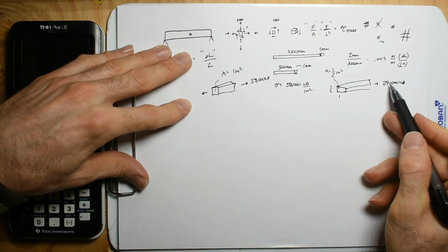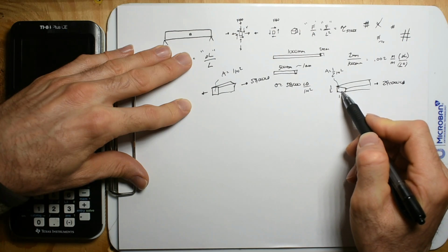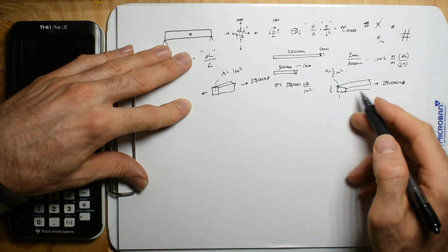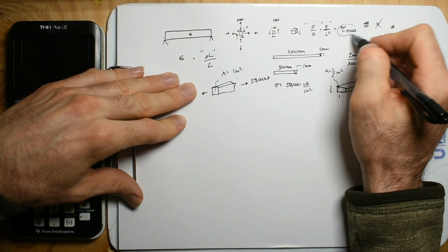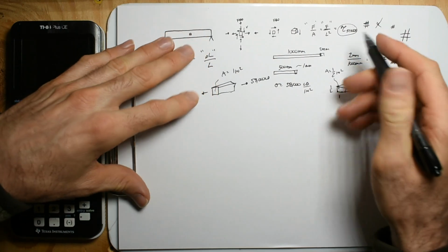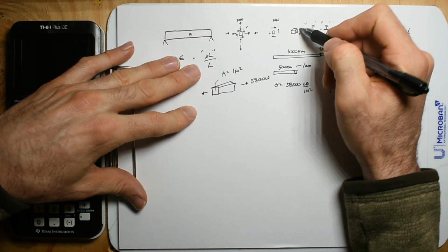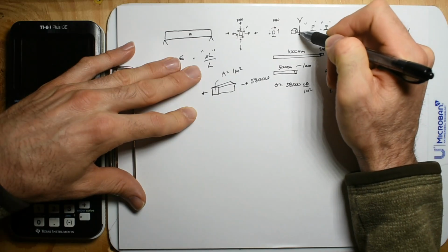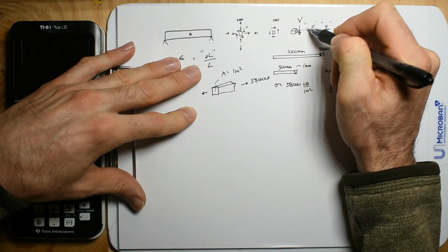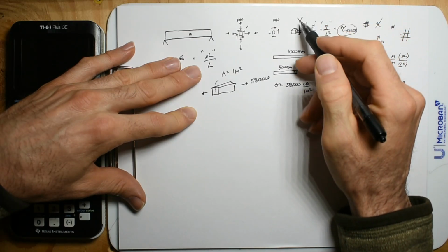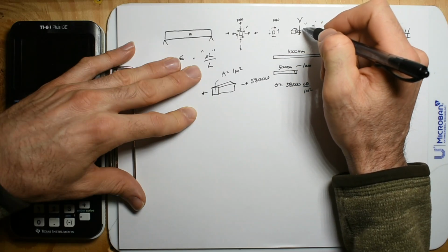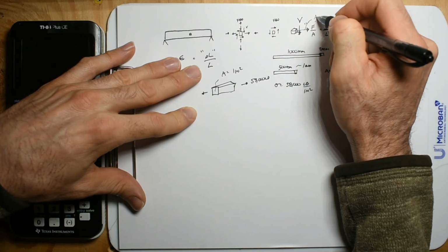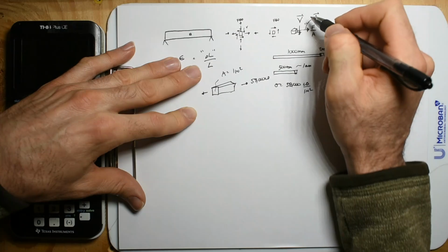And when I pull 29,000 pounds over this area, we talked about tau being the stress or pressure, where this is your shear force, and then here is the direction of your area. The area of a face is always perpendicular to that face, so this would be an area vector. This would be the force vector.